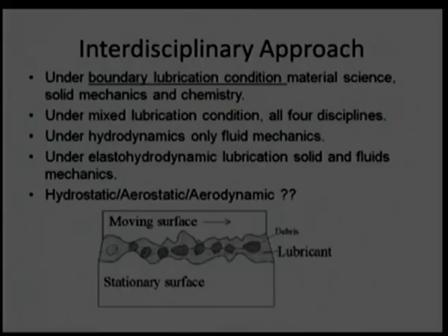In this case, particularly viscosity of air is much lower than any fluid viscosity. So, we need to have much smoother surface for aerodynamic bearing, which is very difficult to achieve. That is why it requires sophisticated manufacturing processes to develop aerodynamic mechanism or aerostatic mechanism.